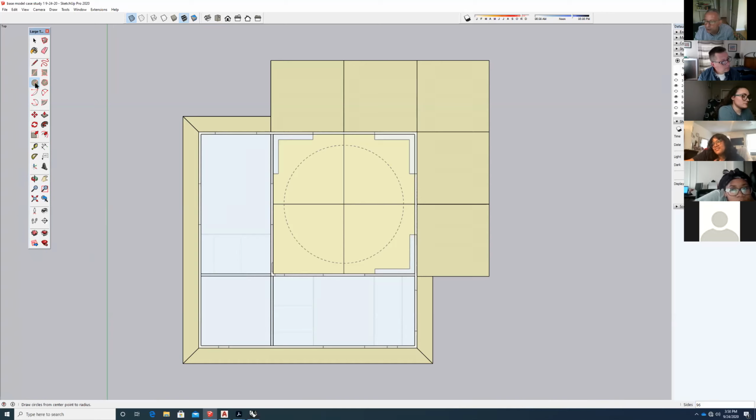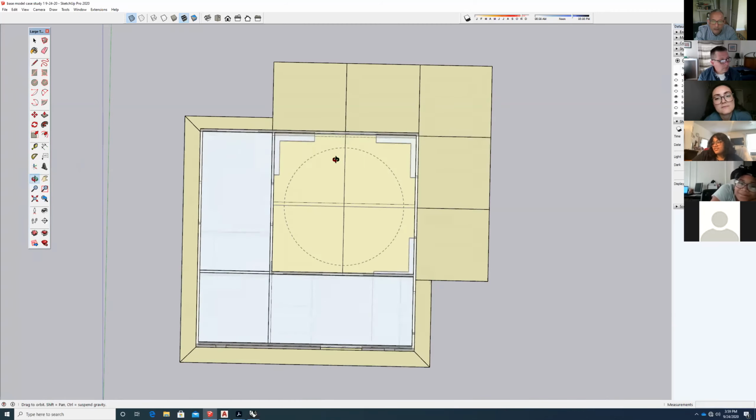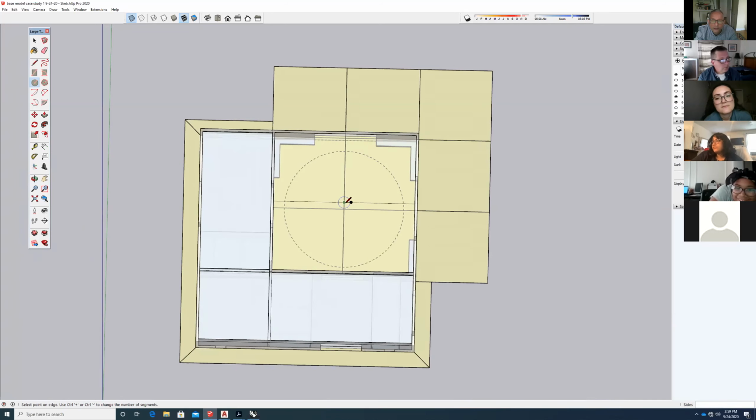I'll show you what the circle looks like if I don't use a lot of sides, but don't do this. I'll just do 12. I'm going to draw a circle now. And you see, that doesn't look like a circle. It looks pretty bad. Let's just forget about it. Let's put it back at about number of sides 96. And now we're going to get a much smoother circle. And I just want to make sure, yep, it's going here.